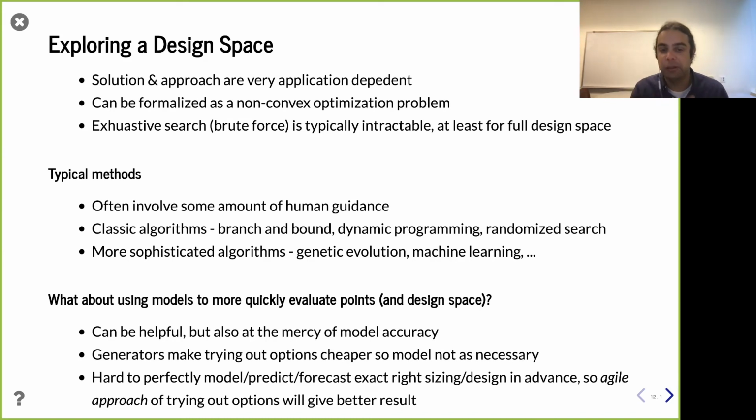And so this is why I recommend closing the loop early. Use your CAD tools for your specific technology to start getting numbers early on, and you can start getting a sense for this and honing in. When you first start on day one for a brand new design, you may have no idea what is the reasonable amount of resources you can use. Can I put down 10 of these blocks? Can I fit 10 of these blocks? Who knows? Push this through a tool flow and you realize, oh my gosh, those blocks are really big or really small, and I can put more or fewer of them than I actually thought I could. So getting that early feedback from the tools really helps you better seed your design process.